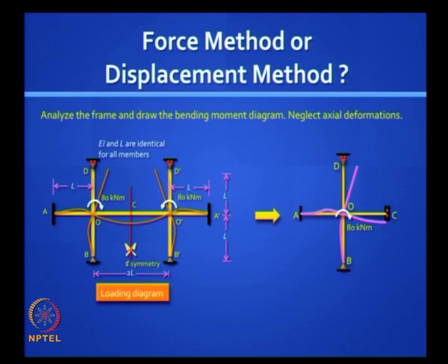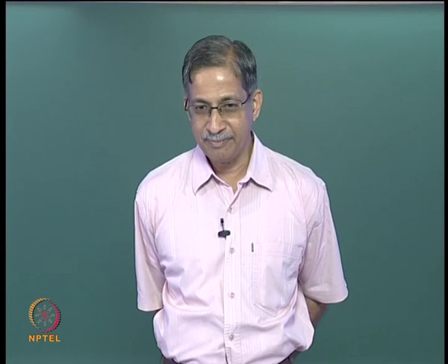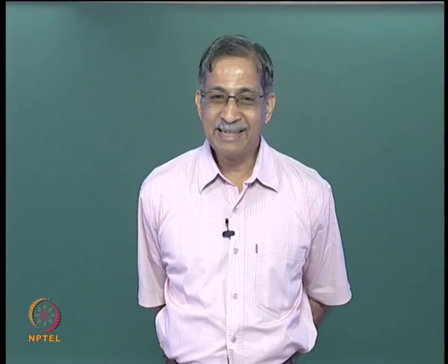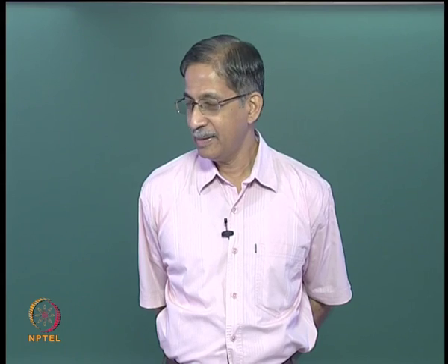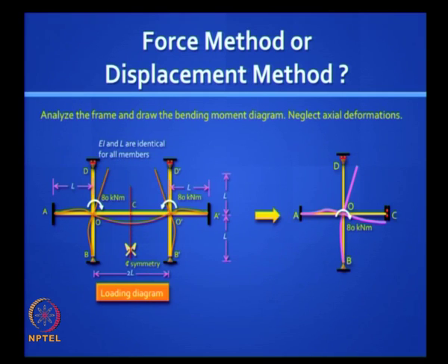If it's just a cantilever, it's determinate, right? So you got some extra reactions coming there. How many of them? 1, 2, 3, 4, 5, 6, 7. Well, at that hinge support you have 2, at that guided roller support you have 2, you have a horizontal reaction also possible, and at the top you can have a vertical reaction 1, so that makes it 5. That makes it 5. What about the unknown rotations?